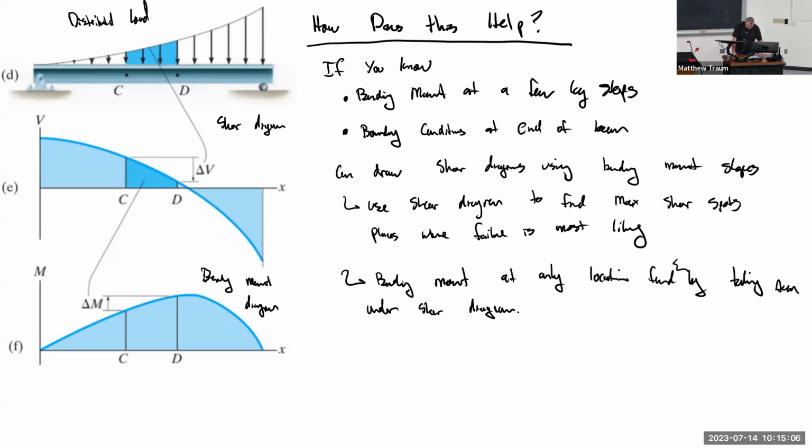So the shear force diagram is just a transition state. We have a distributed load, we integrate once, we use a method, we get the shear force diagram, and then from the shear force diagram, we get the bending moment diagram. We cannot just jump from the externally applied force to the bending moment diagram. No, we need some transition state. That is the shear force diagram. So you check the slope, or you take the integration area.